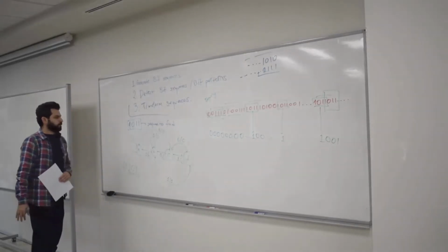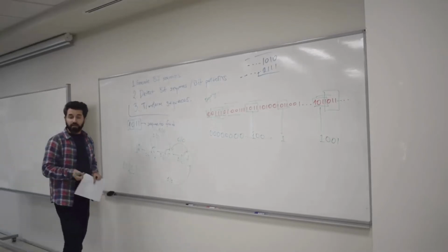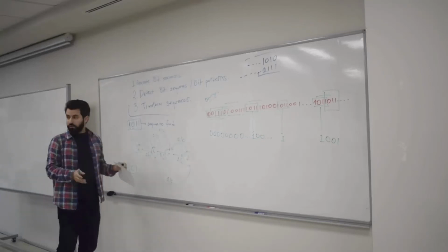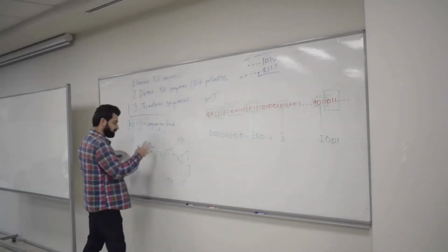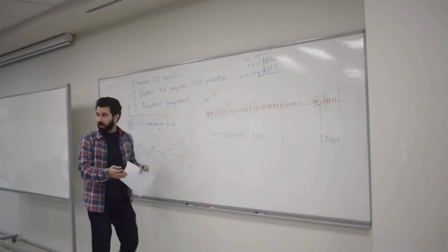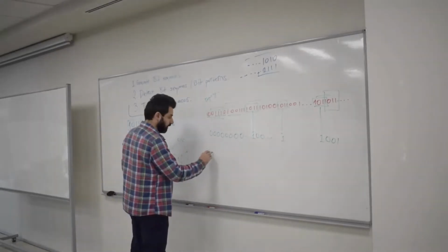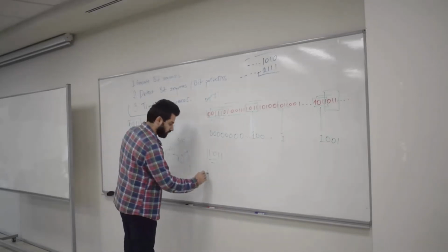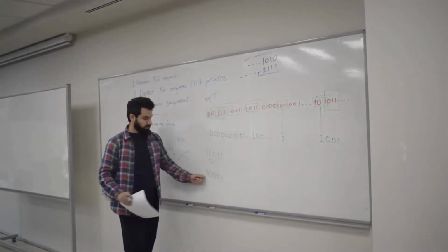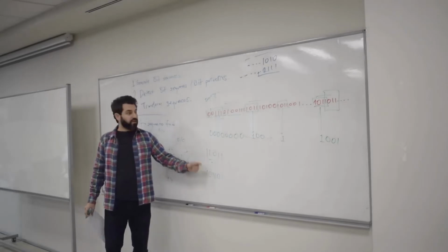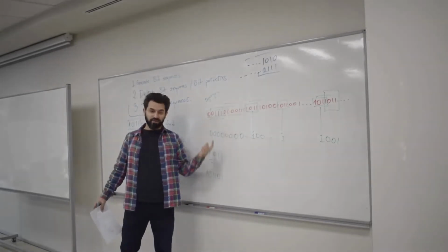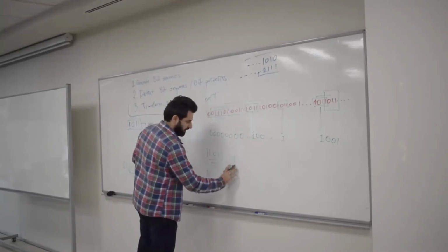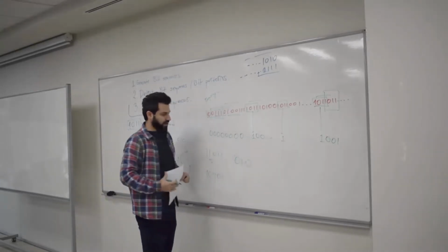Now, in order to digest this material, I would strongly recommend that you draw the same state diagram using other sequence patterns, such as 1, 1, 0, 1, 1, for example. That might be a good example. Or maybe you can choose 1, 1, 0, 1. Those symmetric patterns are very interesting because they create those overlapping problems. But for instance, 0, 1, 0 is not very interesting.